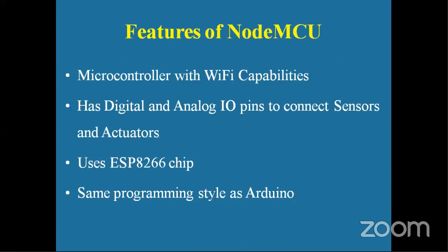Okay. Now the features of NodeMCU very quickly. It's a microcontroller with Wi-Fi capabilities. It has got digital and analog pins to connect sensors and actuators. It uses the ESP8266 chip. Same programming style as Arduino, which I have already told you in the previous slide.